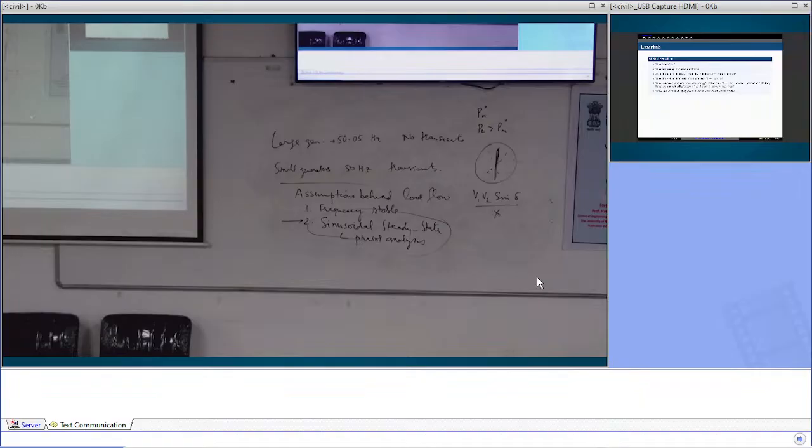So this happens all the time. The electrical power is different from the mechanical power input because it has got the stored kinetic energy. Using that, it could either supply more electrical energy, or it stores more, so it could supply less electrical energy. Right? Now everyone has understood sir's point? Because the kinetic energy is there, I am supplying mechanical power, and on top of it there is kinetic energy which converts to power, and both together form the electrical power. So this is continuously happening.